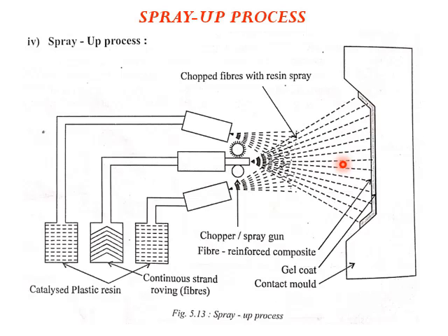Once we finish the process, a roller is applied by a manual method, that is by hand, rolled over this in order to ensure compactness and to remove the air trapped during the spray process. At the corners or at complex shapes, we can apply the rollers to eliminate the air entrapped in the process.